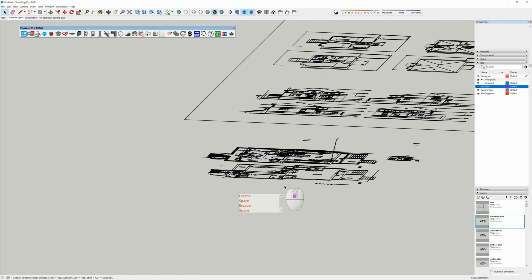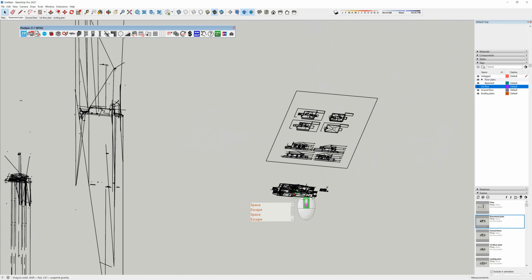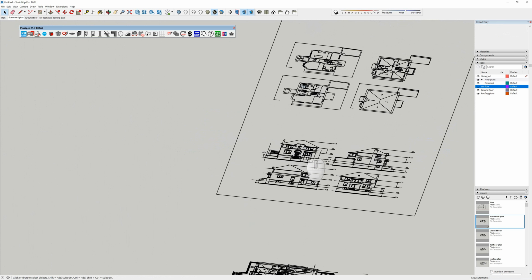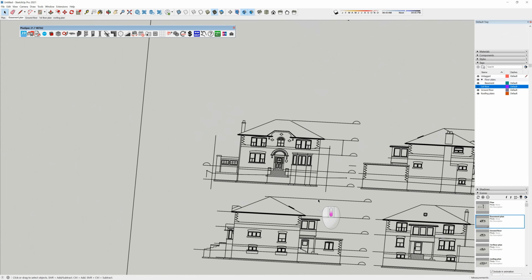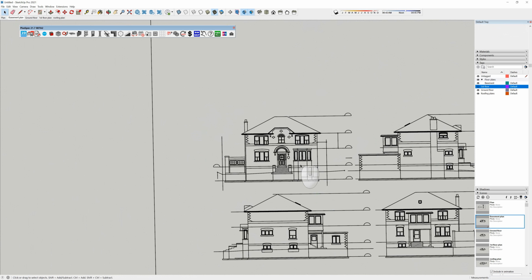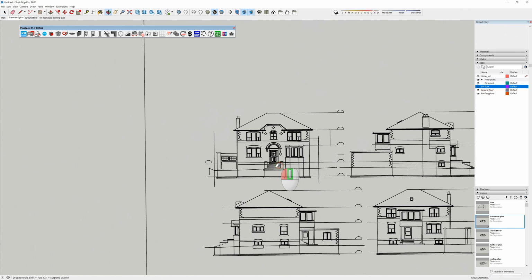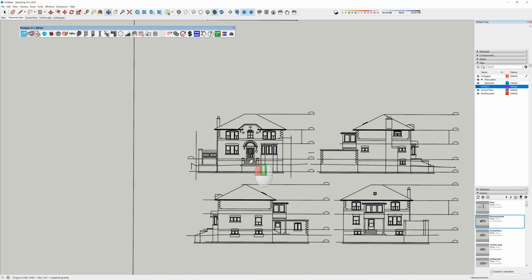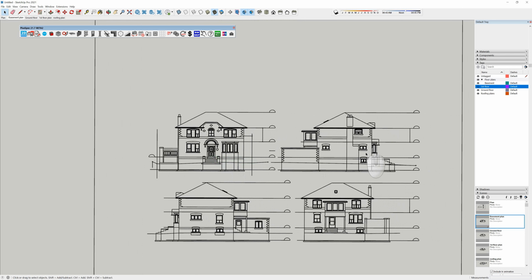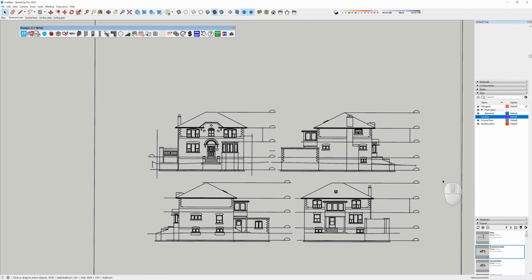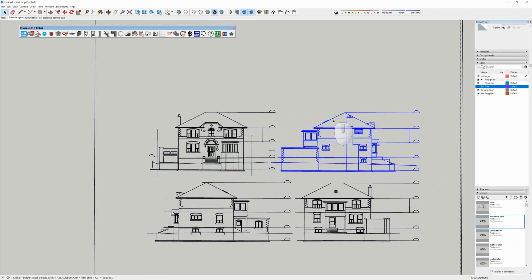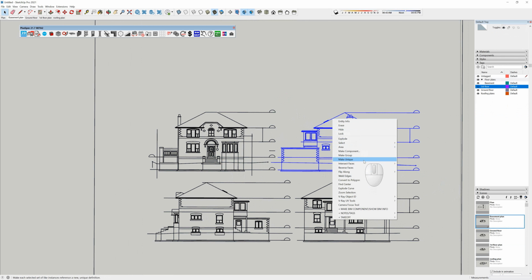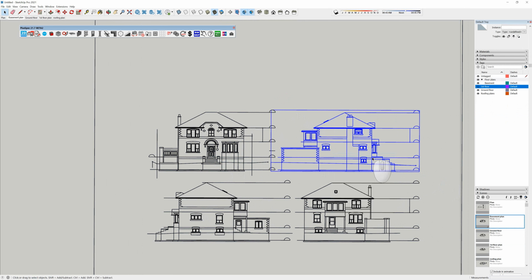But there is one other way we could actually choose our heights. If we took one of our elevations here and we group that and create it as another tag, we could turn it and put it the way we want it to go. So I'm going to use this one here. I'm going to break inside of the group, group this, right click, make group, and I'm actually going to create another tag for this.